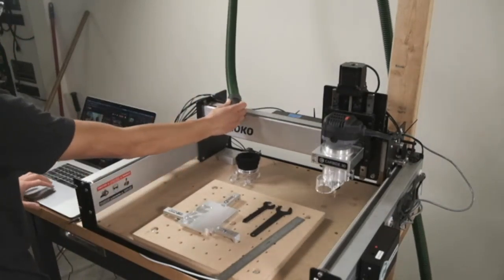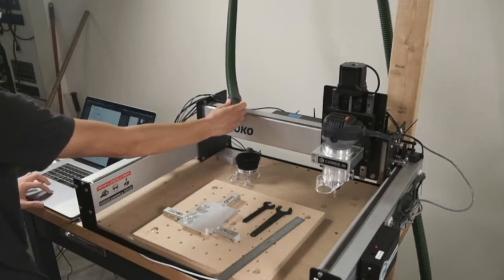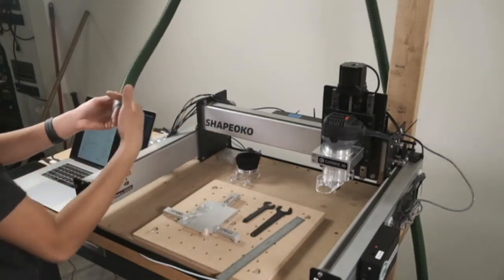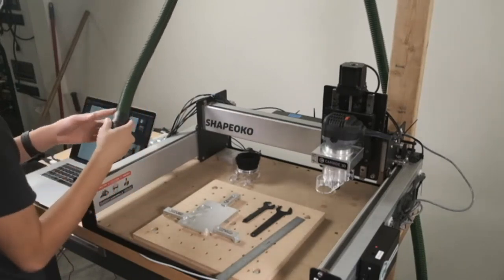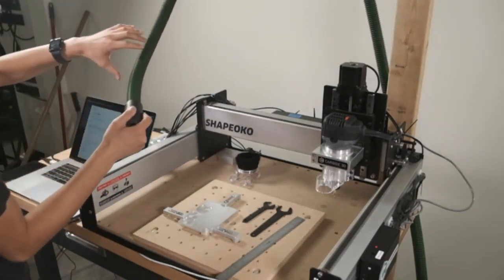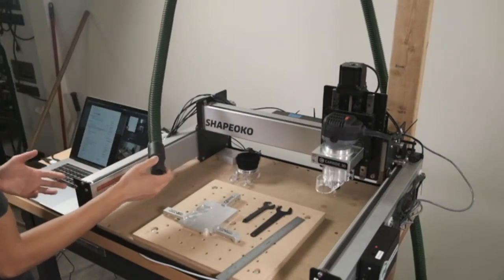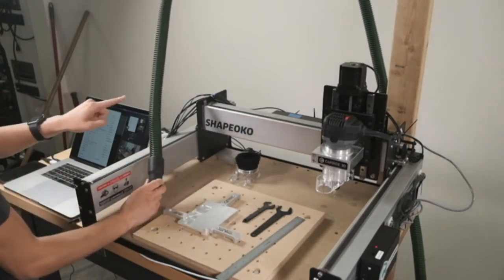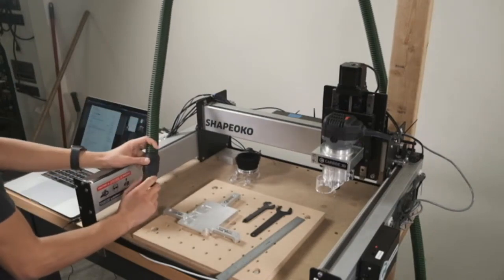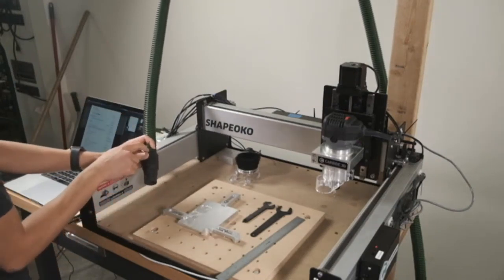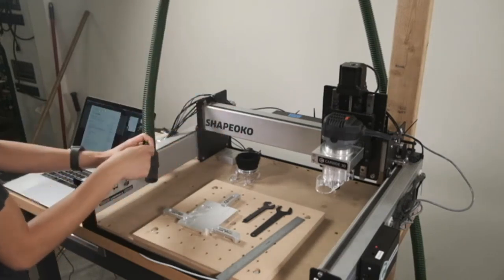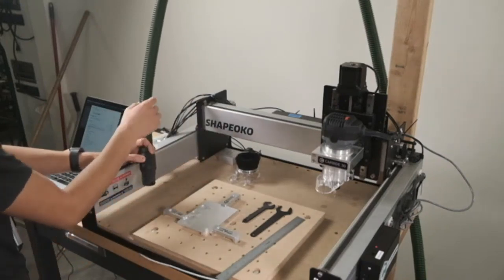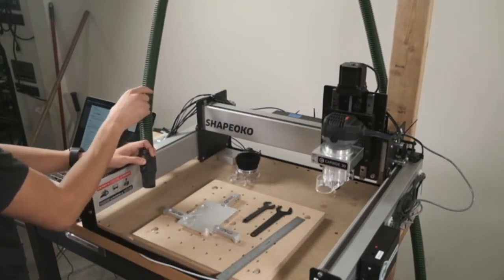This ties into the next question, which is how do you deal with static buildup? As you're collecting dust, those dust particles travel through here. It basically turns this into a little Van de Graaff generator, and this whole thing builds up a pretty sizable charge, and that can cause issues with disconnects and other electronic problems. One of the reasons I stole this from a Festool is that their hoses, I believe, are all grounded. So when you plug this end into a CT or any other extractor, it's got a contact that touches this, and it prevents a charge from building up along the hose.